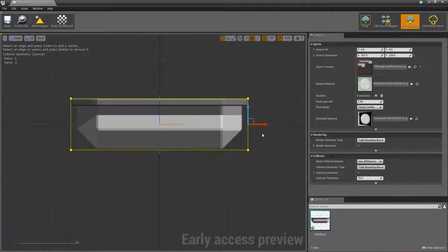So I'm going to click on the right-hand side and press the Insert key to add a vertex. I don't know how often you actually look around a screen when you're using a tool. I know I'm terrible about this, but it actually tells you this in the upper left-hand corner to press Insert and add a vertex, and then you can click on a vertex and hit Delete to remove it. So just to point this out, I'd been using the tool for quite a while before I even noticed that was up there. So I'm going to add a point to the left side and to the right side, and we will slide those up so they go right on the underside of that lip. Like so.